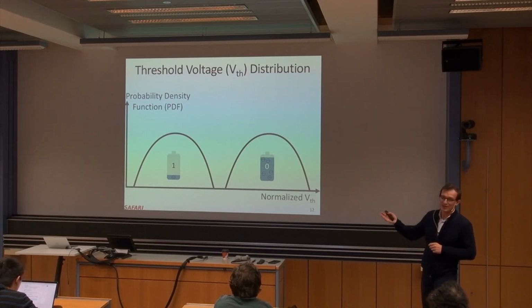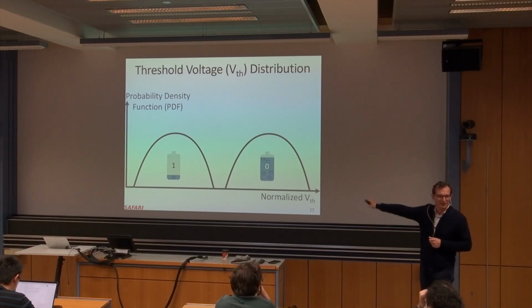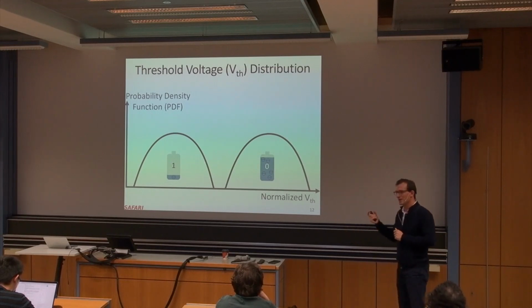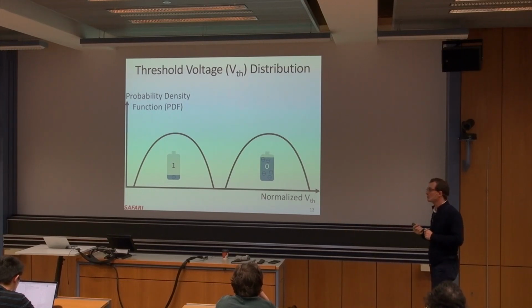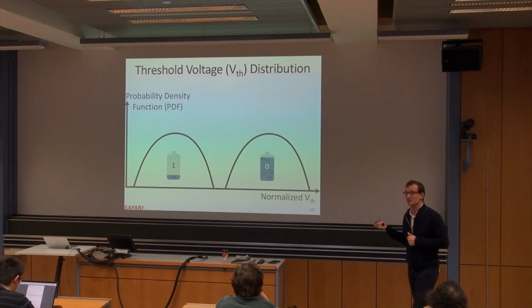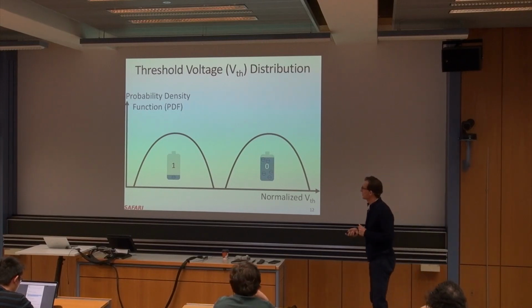I mean, this is also true for DRAM cells actually, if you remember, DRAM cells store different amounts of charge, except we never showed them in this way. We show them in this way because we are a little bit more precise in terms of how much voltage we inject. And we can actually read the reference voltages that we program cells into in flash memory. We have a lot more control because of the machinery there.